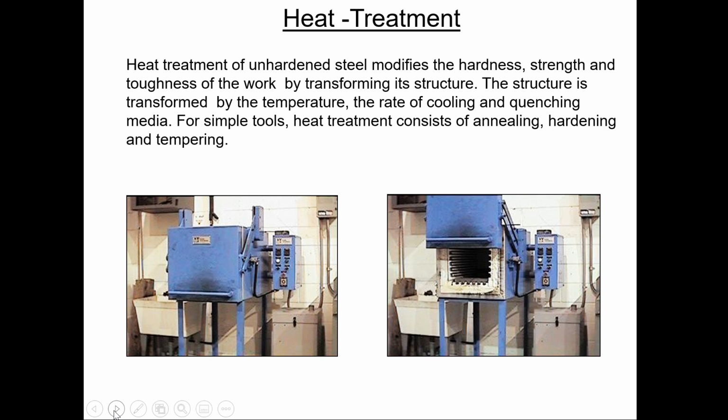Thermal shock comes when you've got a cold piece of tool steel that's just looking for a problem, and you come along and put a 10,000 degree arc on one side of it. It will snap somewhere. It'll crack internally, just at the differential of temperature. A little bit of heat in it messes with the tool steel a little bit. Makes the tool steel think it's not as hard as it was. It makes it think it's a little bit softer. It gives you a little bit more room to play with it.